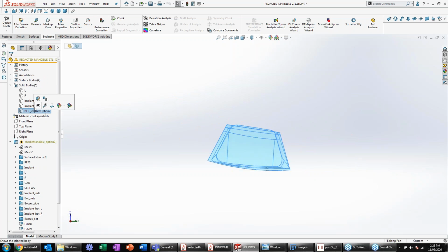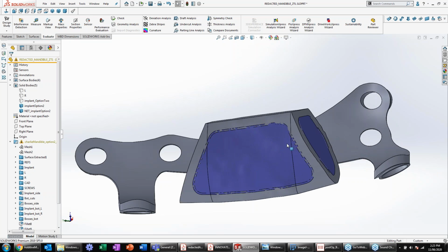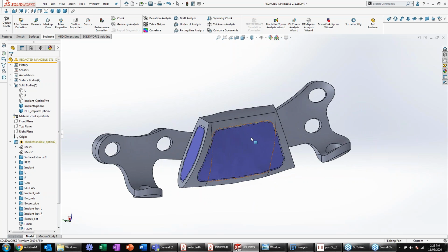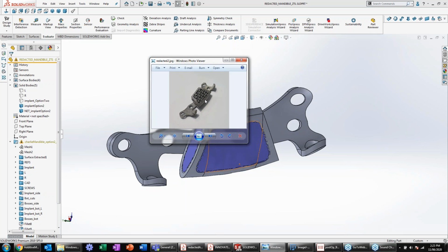but it's something we have to do quite a lot because customers quite often will come to us with a design and they're unsure how to add a porous region. And we have to use a separate software, obviously, to design that lattice structure. So if you ever send a file to us or another manufacturer, we want to have two CAD bodies, a solid one and a porous area, and then we can apply a porous design or structure to that second body.